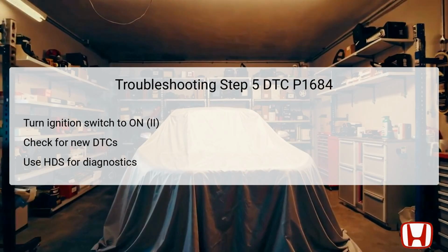The HDS will provide real-time information and logging capabilities to evaluate the performance of various components connected to the throttle control system. Properly interpreting these codes is vital for determining whether the issue persists or if it was merely an intermittent failure during earlier tests. Documenting these findings will assist technicians in resolving the root cause effectively.